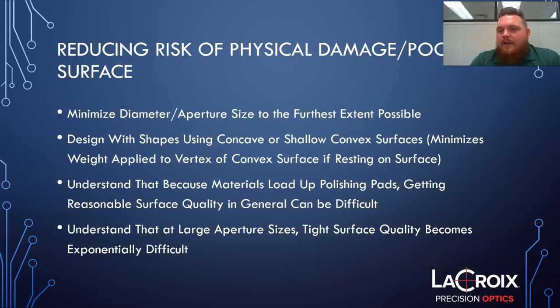And many times for us, we would rather keep the slightly poorer surface quality if it does meet the spec that you have provided, and stick with the current center thickness tolerance that is within spec, than attempt to run it one more time and potentially run them under on CT. When we do run parts under on CT, there's nothing we can do to repair them. There is no longer enough material left to repair and meet the finished spec that you have provided. So at that point, those optics are totally scrapped.